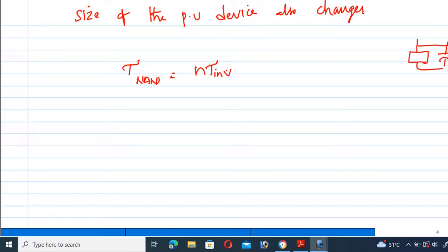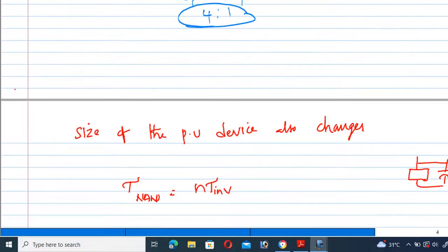Moreover, as a consequence, NMOS NAND gates are used only when absolutely necessary, where the output is low. The number of inputs is restricted so that delay remains within the limit. So this is the conclusion regarding the NMOS transistor. I will explain in Telugu also.